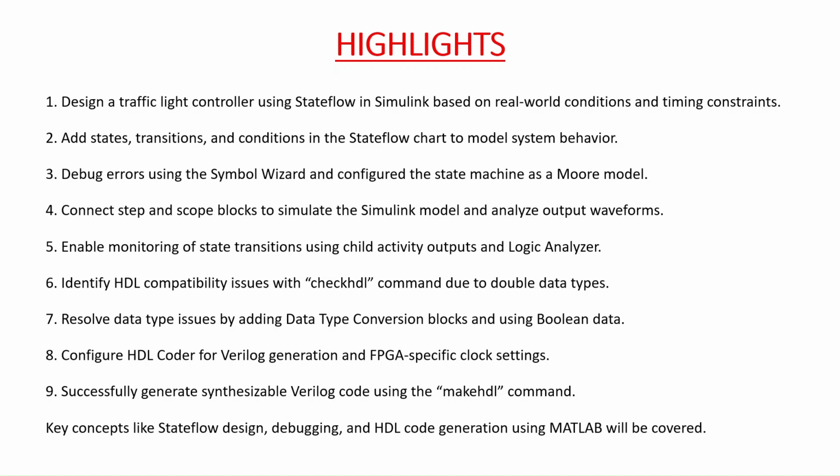So we will identify what are the HDL compatibility issues using the check HDL command due to the double data types that are used in the state model. We will then resolve these data type issues by adding the data type conversion blocks and using Boolean data.